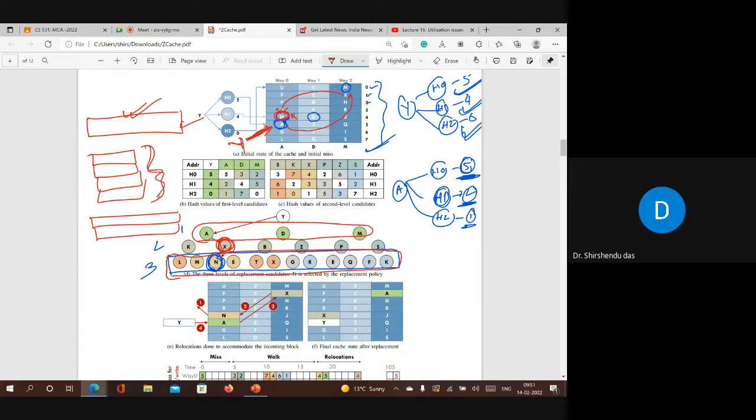And this is the other extreme case: here there are four sets, and each set suppose has four ways, so there are utilization issues. Instead, if you go for only two sets and eight ways, then there will be fewer utilization issues, right? So you can understand this point here. In Zcache, they're trying to reduce the utilization issue by taking a larger group to find the LRU block.